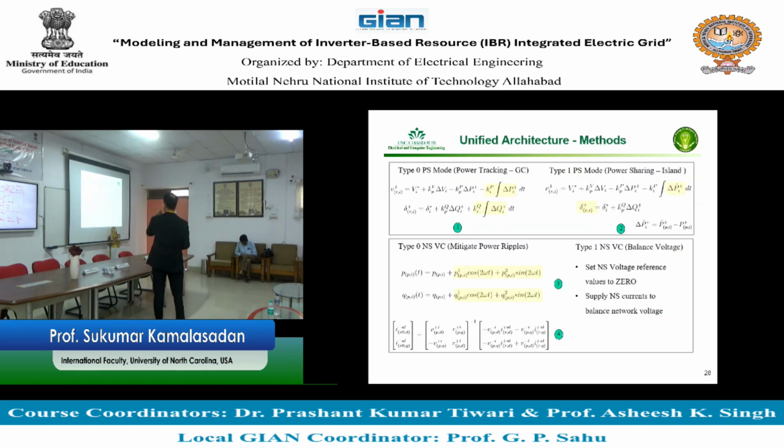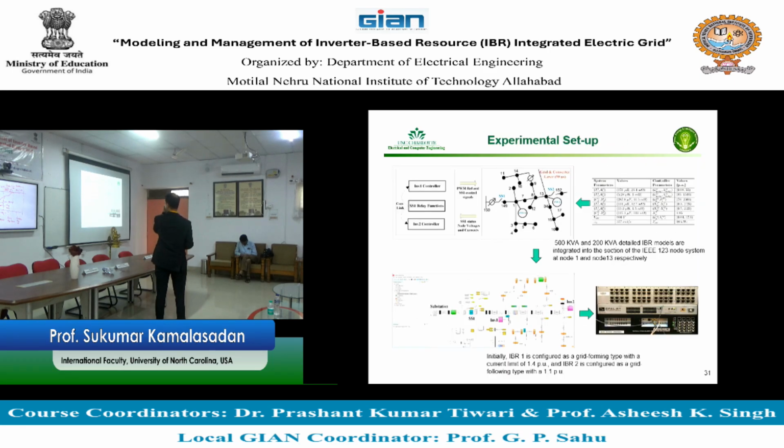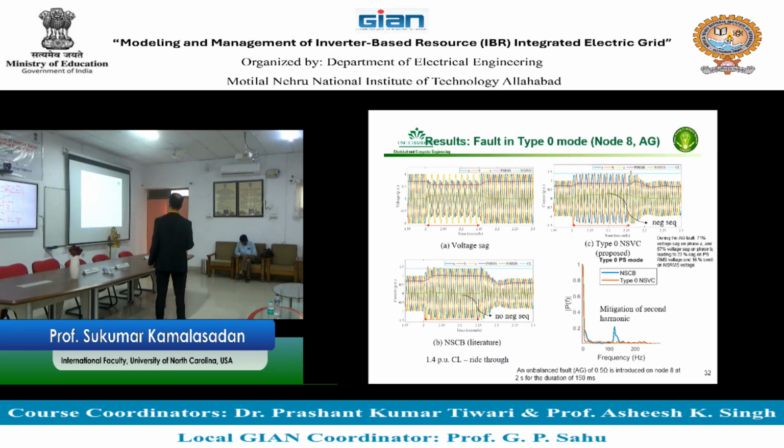So this is tested, some case studies tested in the field too. There's no negative sequence injection in normal operation, but for the method that we have, it gives negative sequence. Because it gives negative sequence, you see the voltage balancing, except for one point, the voltage is limited. It's not shooting high.